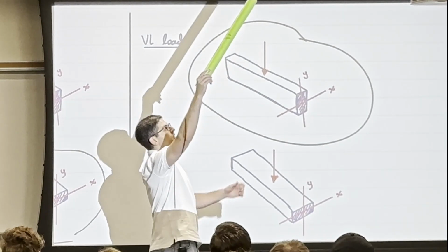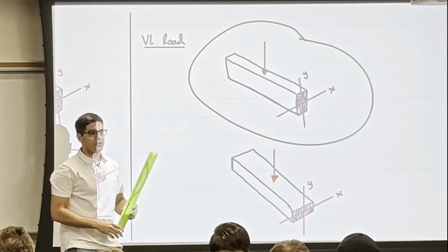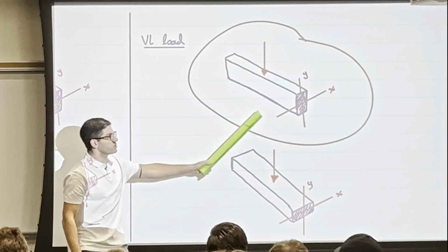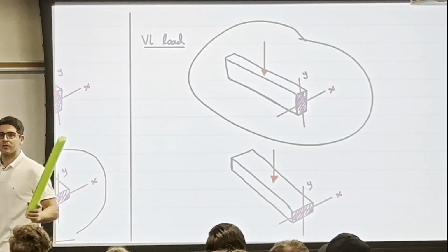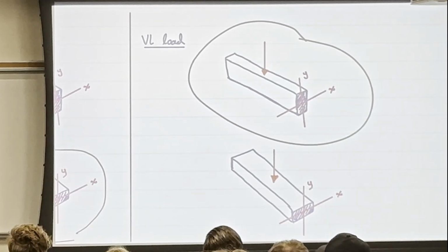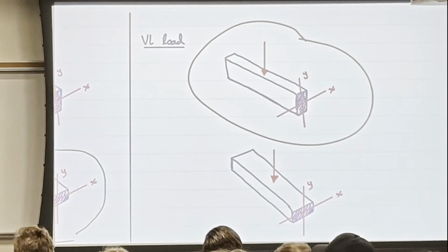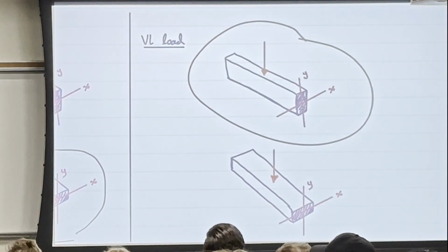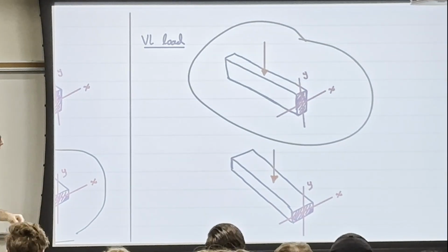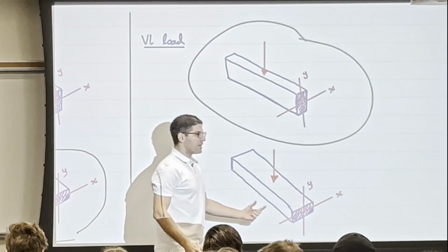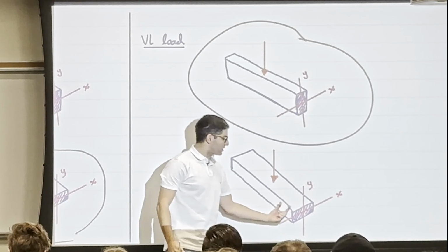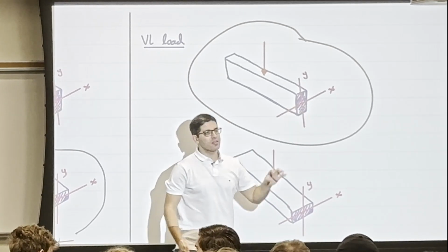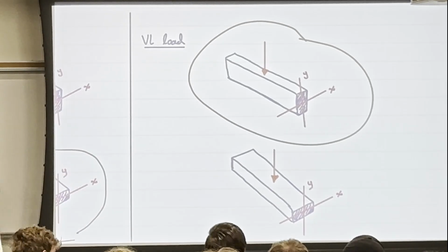He was only able to increase the width. Of course, that's a waste of material that cost him so much. This will cost him less, but he had no choice. The architect perhaps told him, and it makes sense, you don't want me to stand here with a beam above me like this. You'll not see the board. Again, increasing the width is effective, but not as effective as increasing the height.